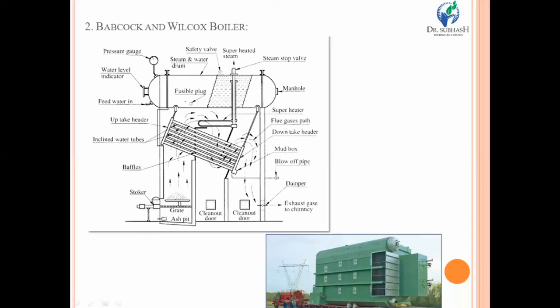That means the initial temperature of all the parts mounted on the boiler is very low. So in order to start the boiler quickly, you need to recirculate the gases again and again over all those interior parts so that they absorb the heat well. In such work, we require damper opening and closing.